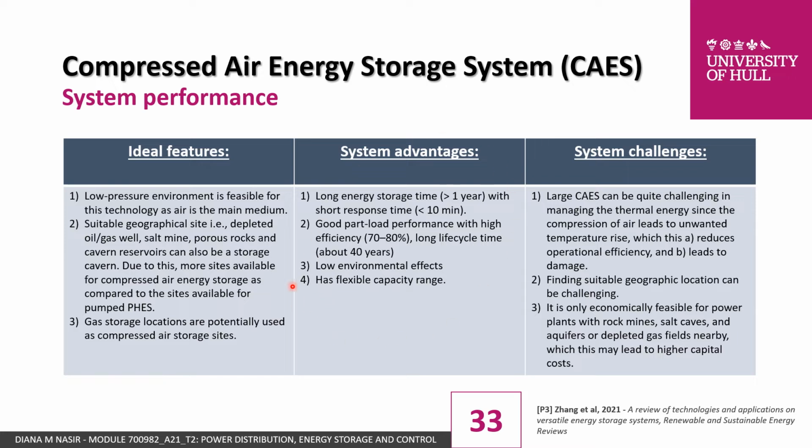The system advantage of it is that it has a long energy storage time, which is more than 1 year, with a short response time, which is less than 10 minutes. It has good part load performance with high efficiency between 70 to 80%, and it has a long life cycle time, about 40 years. It has low environmental effects, and it has a flexible capacity range.